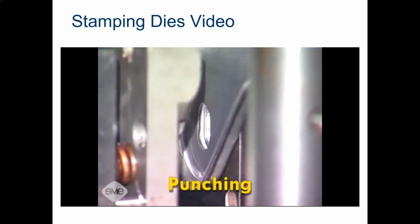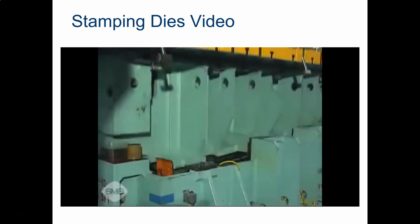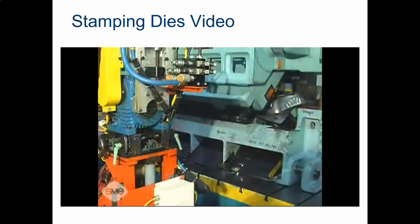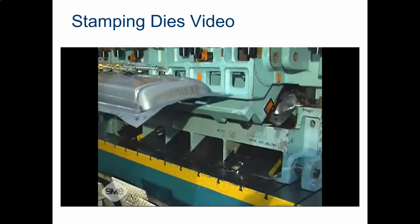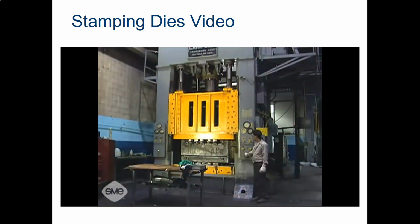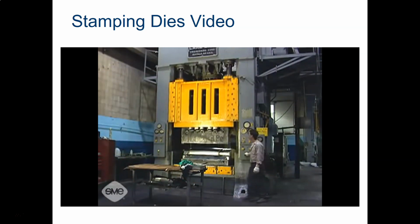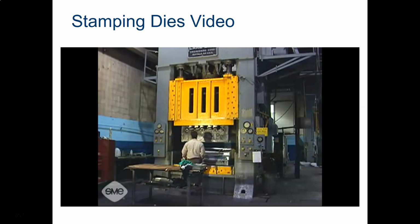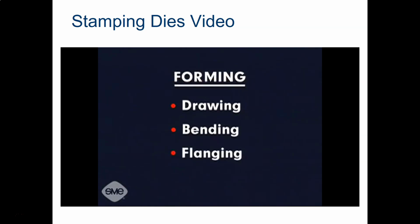Punching is the cutting of a slug from the sheet metal stock to produce a hole. After a part has been formed, a trimming die is utilized to remove the excess scrap metal from the workpiece. Forming is a broad term for metalworking processes in which the shape of a punch and die is reproduced directly in the metal. Some common forming operations done with press-mounted dies include drawing, bending, flanging, and hemming.